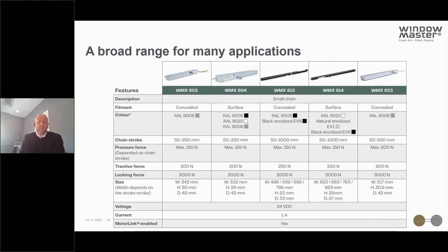and then the size of it, whether it will fit on the window. The majority of actuators that we have are 24-volt DC motors. They tend to be much more friendly for integration into the buildings en masse, and we can do much smarter levels of control with these. They're easier to integrate into buildings and operate on a frequent basis.